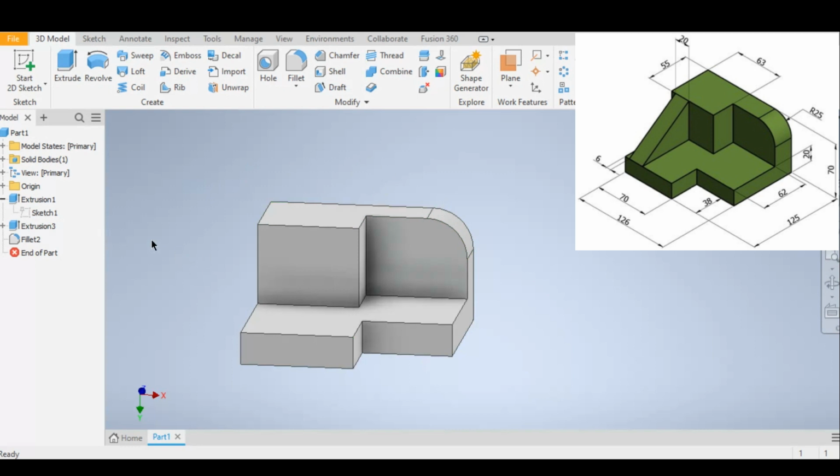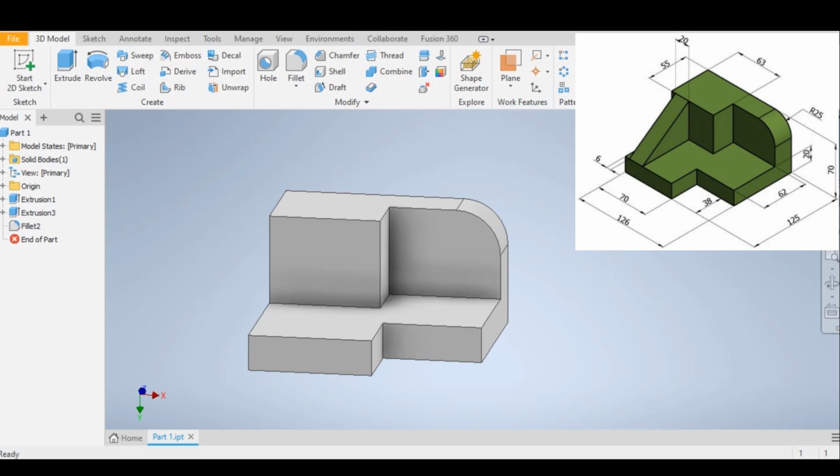So now that this section is complete, we can start to work on this new diagonal section that we want to add to our drawing. To get our diagonal section on our 3D model in this area, we are going to sketch a 2D sketch, and from there extrude this and join this to our existing 3D model.